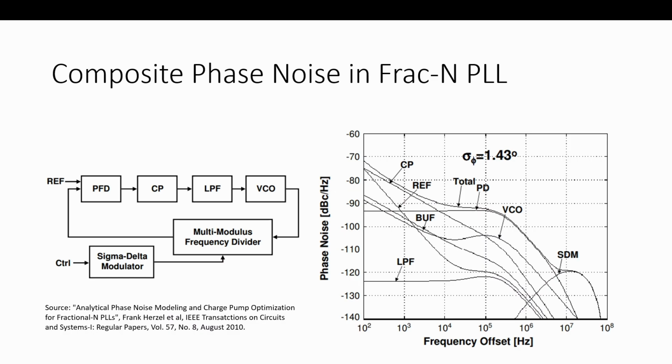Like the VCO would be its phase noise. This SDM is the delta sigma modulator, what its noise is, going from the node into this node here as a noise source, going to our output at the VCO output. So you have several opportunities of injecting inputs, and you can do that with this approach as noise models. You could say, hey, I have a power supply noise that gets into here, and you can inject that into the loop filter, the active loop filter. Figure out how clean does it need to be, because the output is going to be the composite of all these noise sources that we're seeing versus frequency.